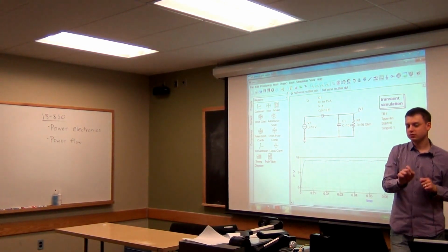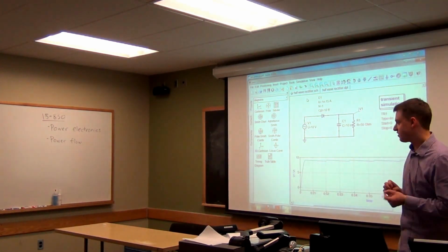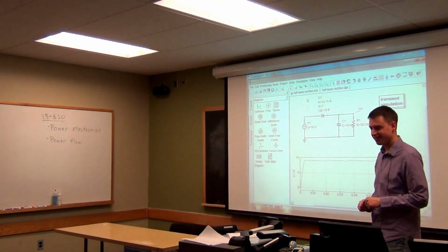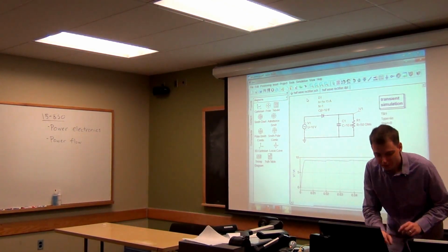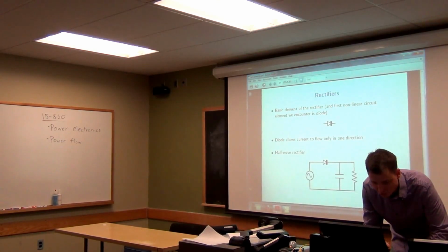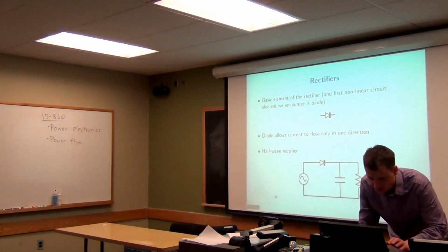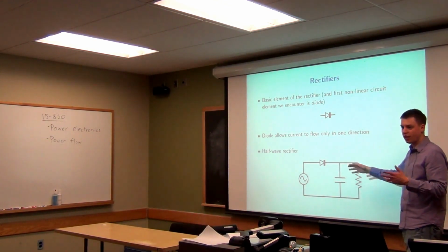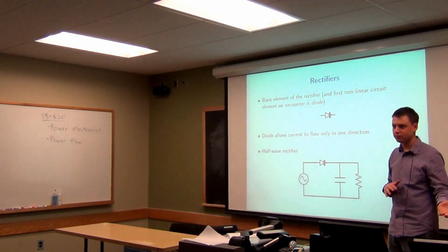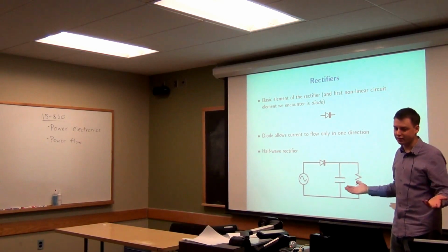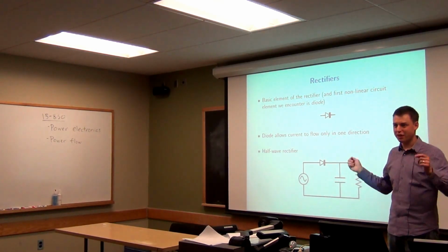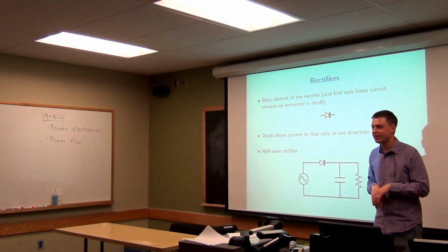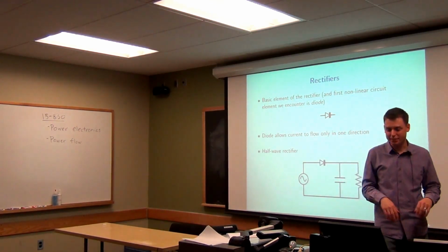All right, so I'm going to show in a second how this relates to what we saw in our little plot before. But before doing that, I'm going to describe one more thing, which is this seems kind of inefficient, right, this half-wave rectifier, because we're essentially ignoring half of the signal. We're just throwing it out. Whenever the voltage is the other way, positive over here, negative here, we're just going to ignore it and not use that power at all.